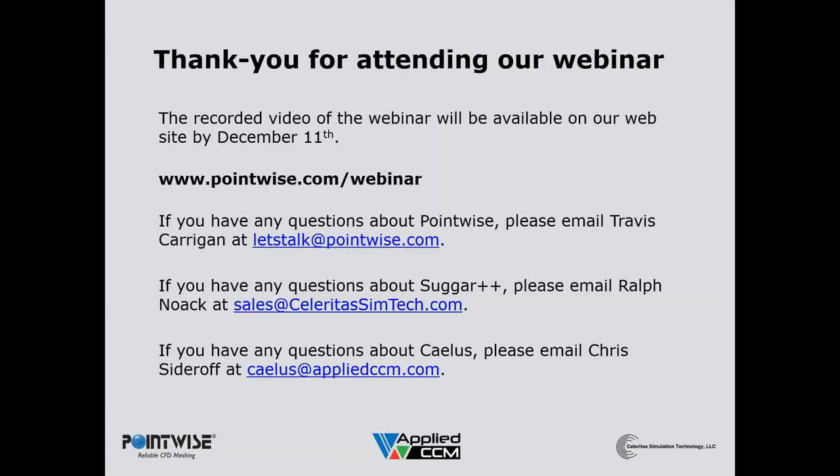Okay. Does the Caelus overset capability use implicit or explicit block coupling during the linear solve step? That is a good question. I'll have to ask my partners directly about that. I know there's a direct matrix manipulation, so I guess it would be handled implicitly. We've taken one particular approach for doing that, and it is still implicit because we're manipulating the matrix directly at the overlap locations. But there are also some alternative ways that we may have to consider depending on solution quality and solution stiffness.